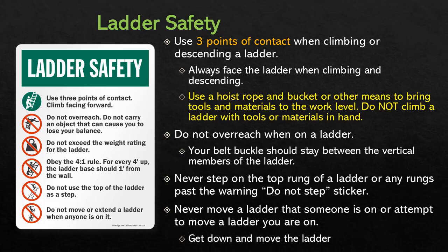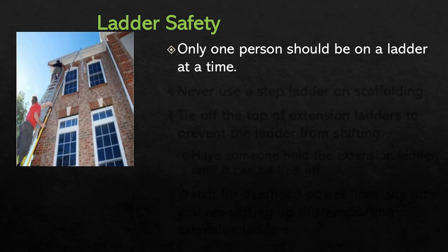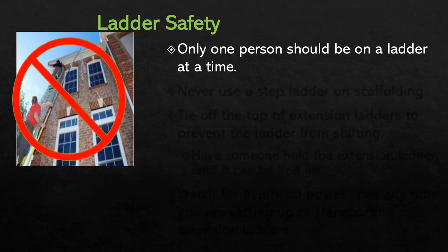This should go without saying, but never move a ladder that someone is on, and never attempt to move a ladder that you are on. You should get down and move the ladder. Unless a ladder is specifically designed for more than one person to be on it at a time, which most ladders are not designed for and are not rated for, therefore, under almost all foreseeable circumstances, only one person should be on a ladder at a time.